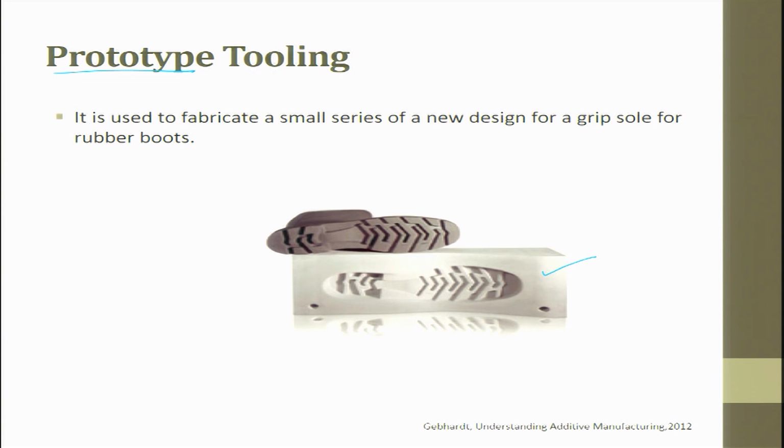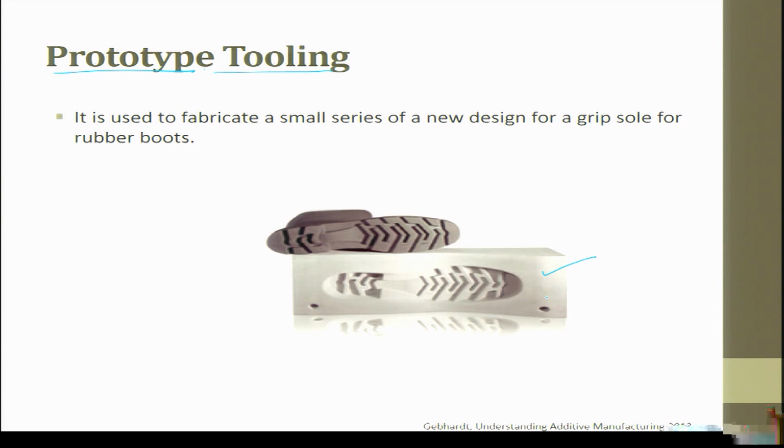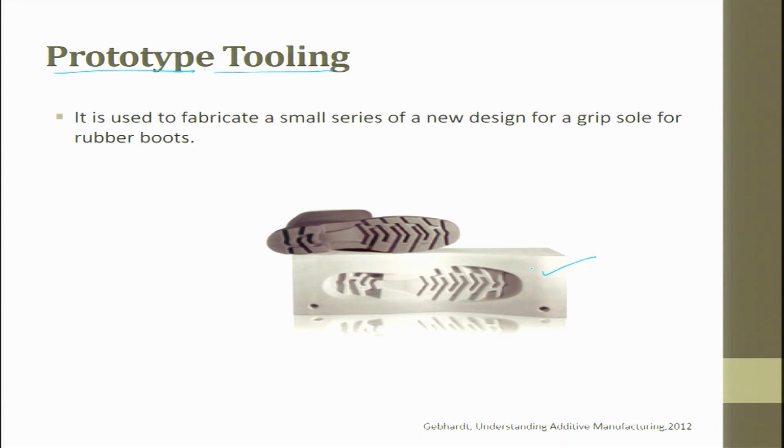You should also understand that making tools or dies for mass production is expensive. So, only for that we are talking about the concept of prototyping of tools. So, here the tool is made as a prototype, and after this the corrections will be made and the final design will be accepted, and directly this tool will be produced. That is called rapid tooling.